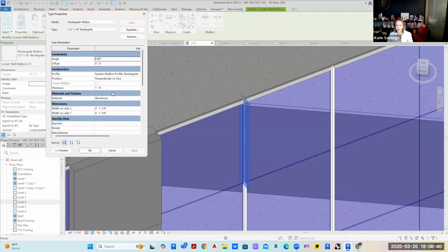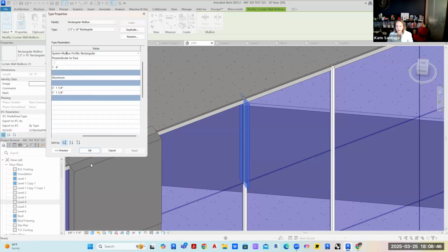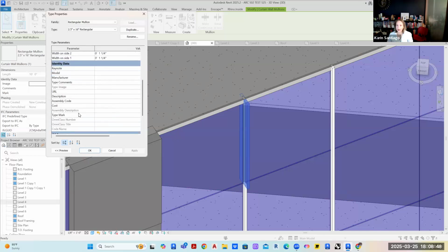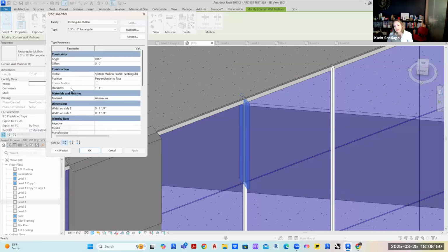And there is a way to create an offset that I am looking for in here. There we go. So you see it up here. The offset is how you tell Revit to move this one way or another. I can't remember if it will push it out or in, depending on whether this is negative or positive. So I'm just going to trial and error this.